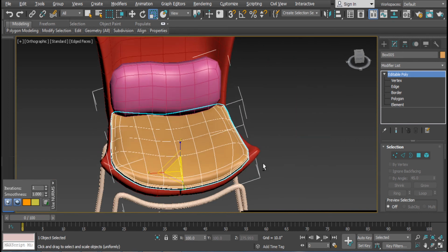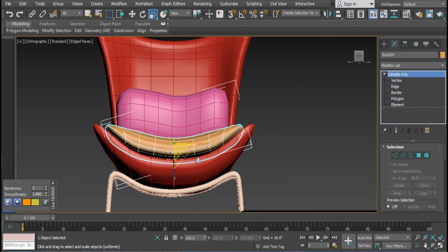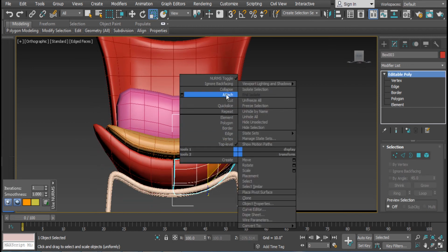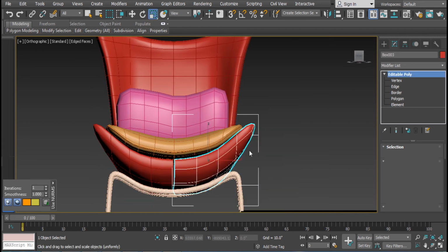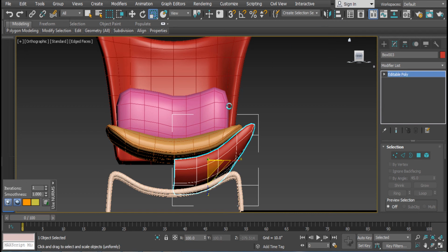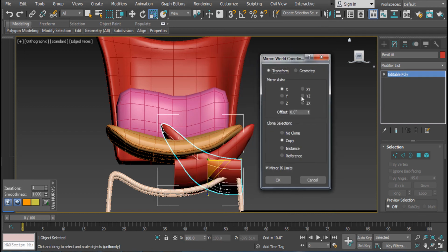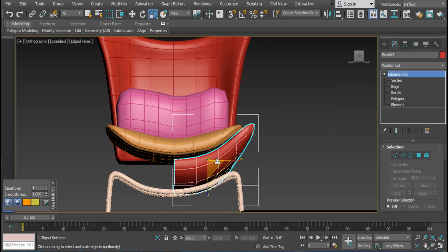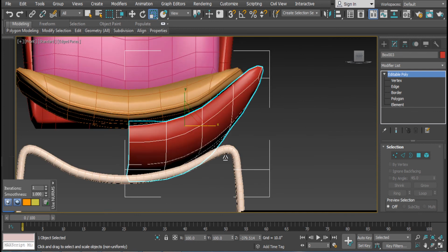Okay, the similar technique: attach to the other object, select the in-between vertices and scale the vertices, which is almost right. Then select the weld option and increase it as much as you need for the mid vertices.